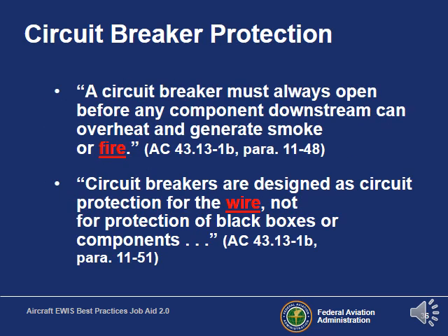So a circuit breaker has to always open before any component downstream can overheat and generate smoke or fire. The circuit breakers are designed to protect the wire, not necessarily the components, but they should be able to protect the wire from overheating and causing damage.